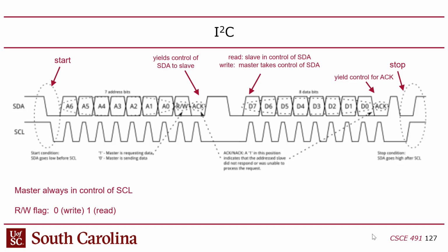I'm the master. So when you send data, unlike SPI, which is edge triggered, remember we talked a lot about how you use CPOL and CPHA to figure out what edge of the clock you're reading data. I2C is different. It's not edge activated. I2C uses a level sensitive clock, which means that, in other words, hopefully you learned about latches versus flip-flops when you took... okay, good, I'm glad to cover that.